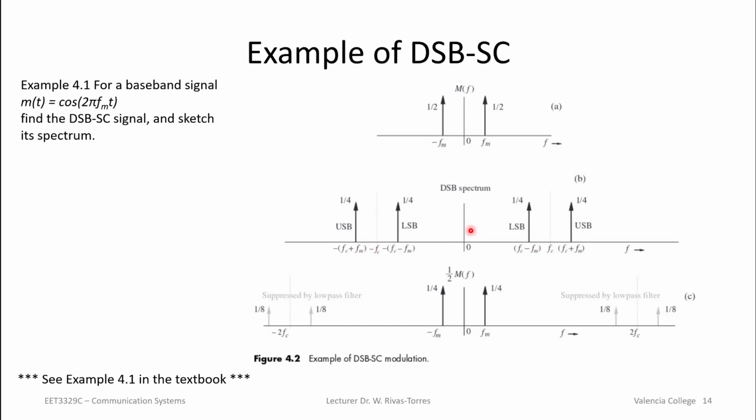And the same thing happens to the one that shifts to the left. There's no carrier. And now you can see why we call this the upper sideband, and this is the lower sideband. Anything above fc is what we consider the upper sideband, and anything below, the lower sideband. On the negative side, it's the other way around. But remember, we normally don't speak of this in actuality. Again, this is that mathematical thing that we were talking about.